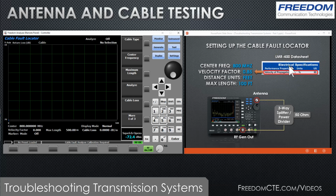So look at the cable, look at the part number, Google the part number and data sheet, and you should find something that says velocity factor or velocity of propagation. It's in percent. In this case, it's 85%. So we will enter a value of 0.85. I'll do that right here, 0.85, and press enter.